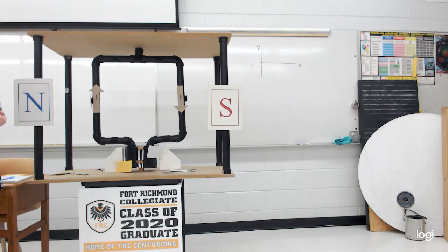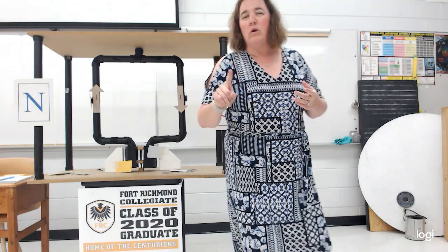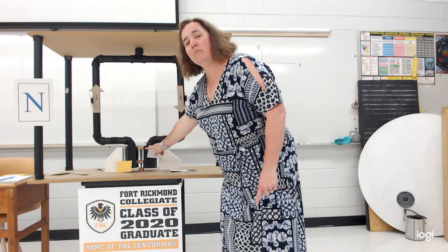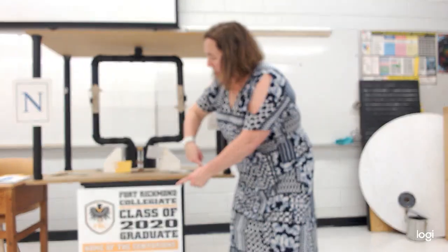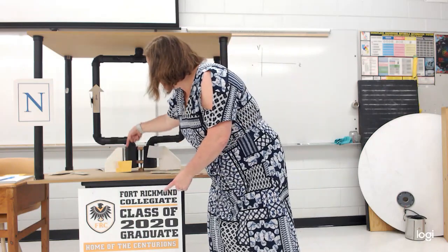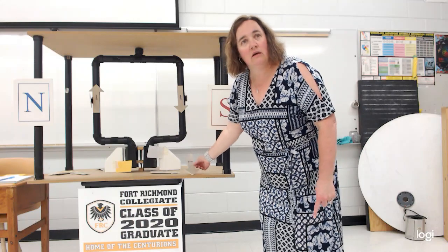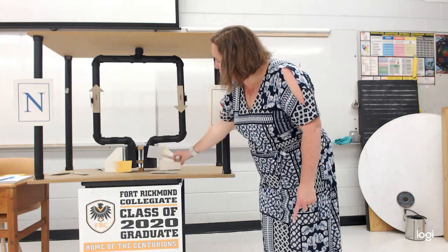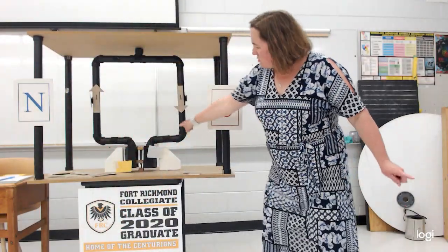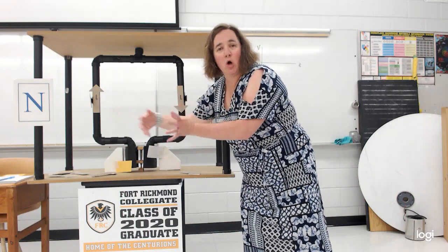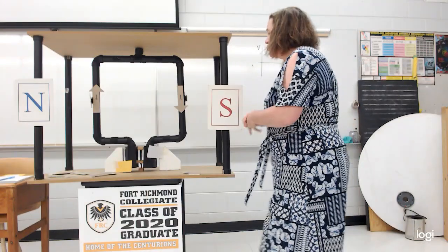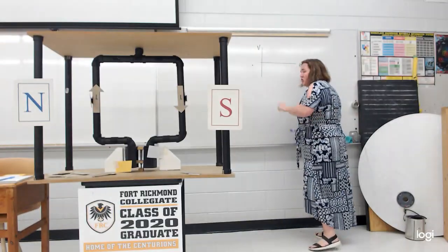Okay, so that's exactly what we did before, but now when we follow that current, it comes around the armature, goes into the commutator, out through the brush, and around the external circuit, kind of this way, coming around, in, and there. I don't know if you guys can see that current vector coming out here. I'm representing it coming out this way, and then we could say current is coming in that way. So current comes out, goes around, lights a light bulb or powers something. So that's during our rotation. So we're generating a voltage at this point.